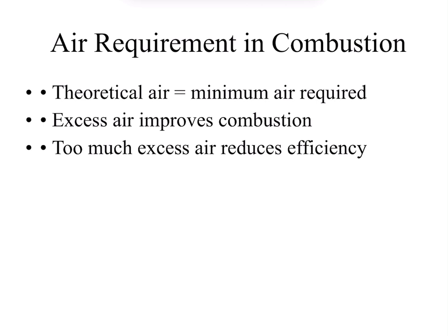Excess air improves combustion, but if it is too much, it will reduce the efficiency. So we need to put it just nice, like 150%, so we will have 50% excess air. It is not too much, and the excess air is there.